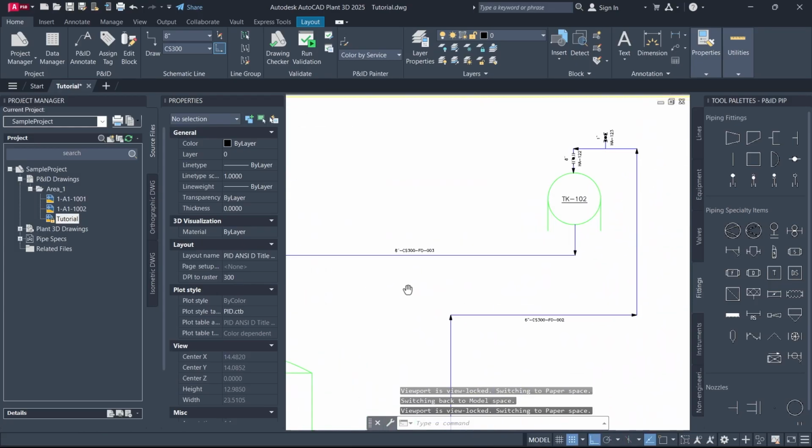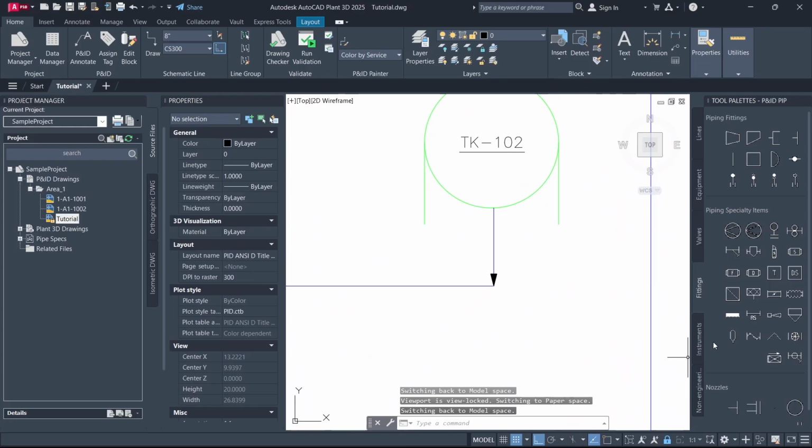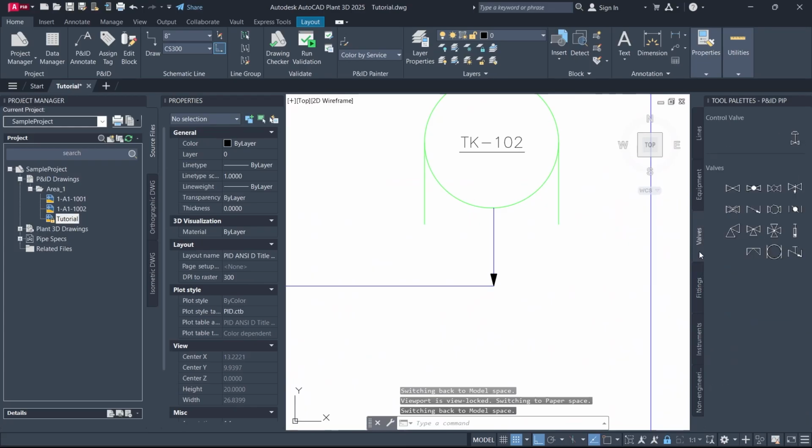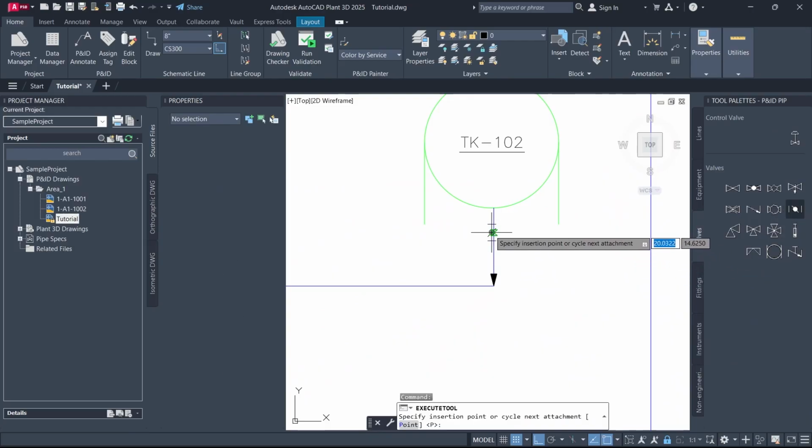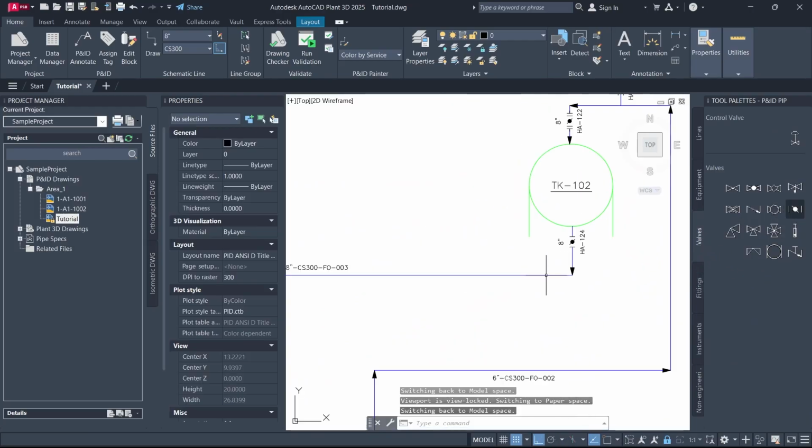The upper side is now covered. The last remaining area is the gravity flow line back to the lower tank. Add an isolation valve near the tank connection. We will not add extra drains here, so the line stays simple.